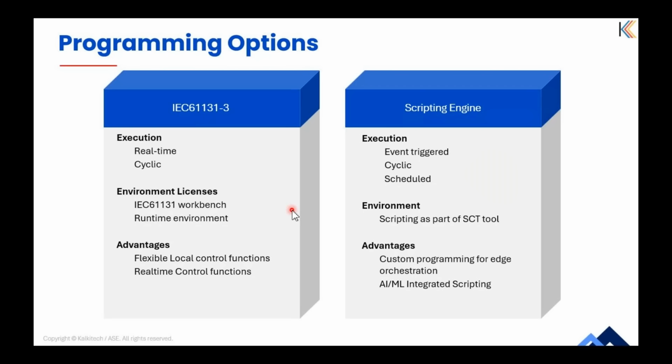Alternatively, we have a versatile scripting engine which is based upon the Lua language, Lua scripting. This allows for more customized logic, supporting event triggered or cyclic or scheduled executions. Its advantages include enabling complex edge orchestration and even integrating AI or ML models directly into our control strategies via scripting.